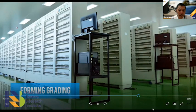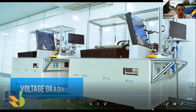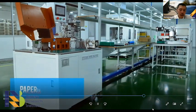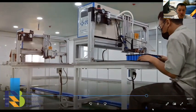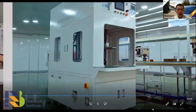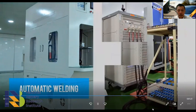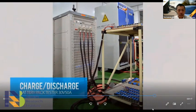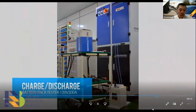After finishing, the cell will be activated: forming and grading. And then if we need the pack, we go to this area, grading the cell, putting the insulator on the terminal, and then doing the combination, serial and parallel, with manual welding, or we can use automatic welding. After that, there's a pack we can test. We do the testing at small voltage, medium, or high voltage, depending on what kind of pack.